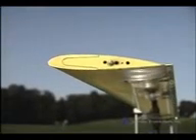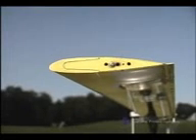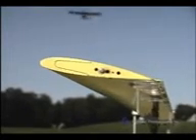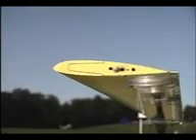The way we generate lift is through an airfoil. Airplanes have wings. Helicopters have rotary wings called rotor blades. If the speed of the airfoil increases while moving through the air, the lift also increases. Lift can also be increased by changing the angle of the airfoil relative to the direction of movement. This is called the angle of attack.